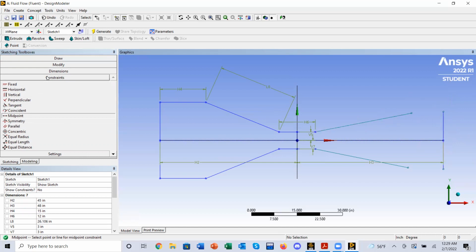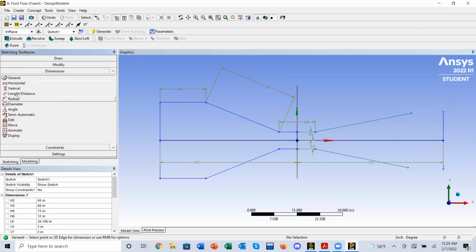But first we'll define the angle. So if you go into dimensions, it should be an angle tool. Now I could have added another line right here and made it easier, but then when you delete it, it's just on dimensions. I'd rather keep as many dimensions as possible. There's a couple ways you can do this. I think if I go this way, then I gotta go like 177 because we want an angle of 3. Yeah, so you kind of want the opposite because it's just the way the tool works in this case.